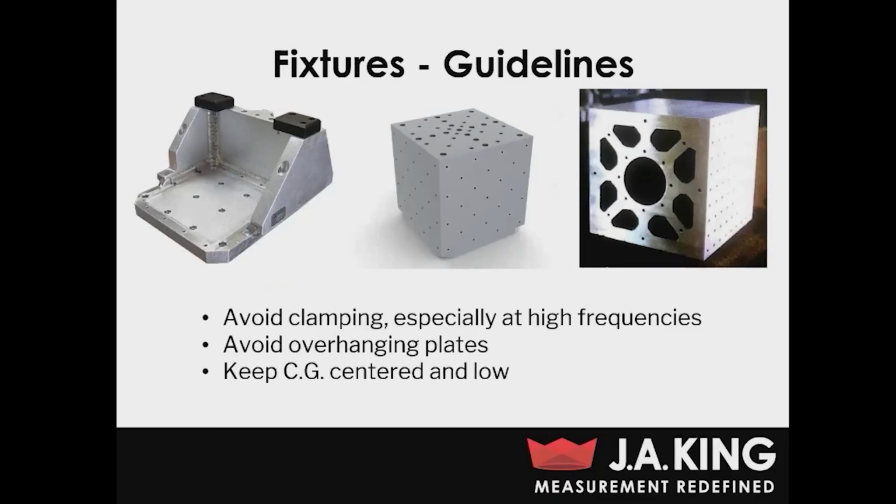So I also just want to point out a few guidelines when you're designing fixtures. You're going to want to avoid clamping when possible. I did mention clamping earlier in this presentation. We do use clamping sometimes, and you can use it, but you just have to be careful when you use clamping. You want to make sure that you use it mostly for tests that aren't very aggressive, and especially tests at low frequencies. And if you do clamp, you want to make sure you take note of the exact placement of those clamps. That way you've got a good repeatable test, and if you need to rerun anything, it's easy to do so in the exact same configuration that you ran it initially.